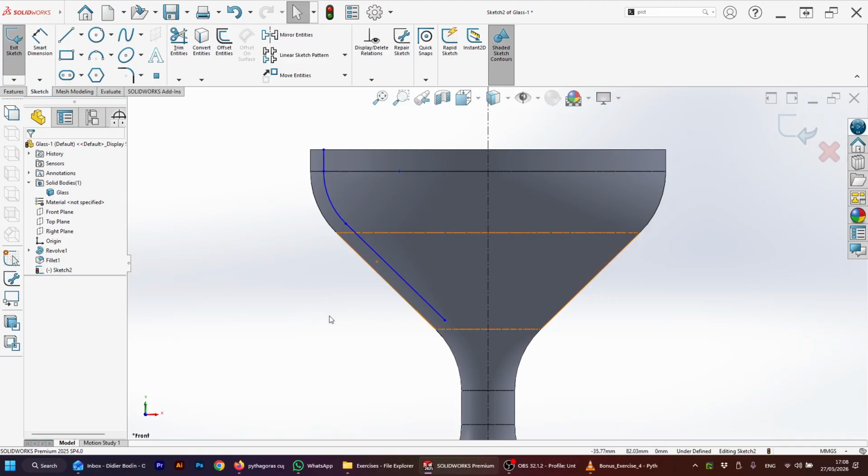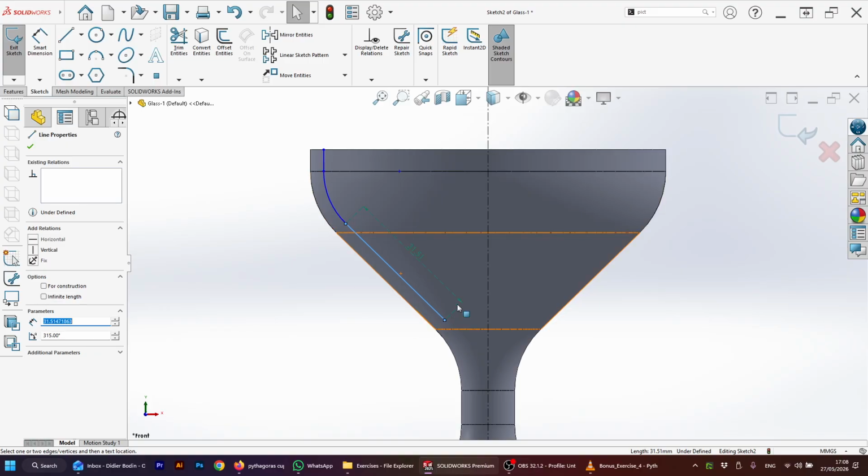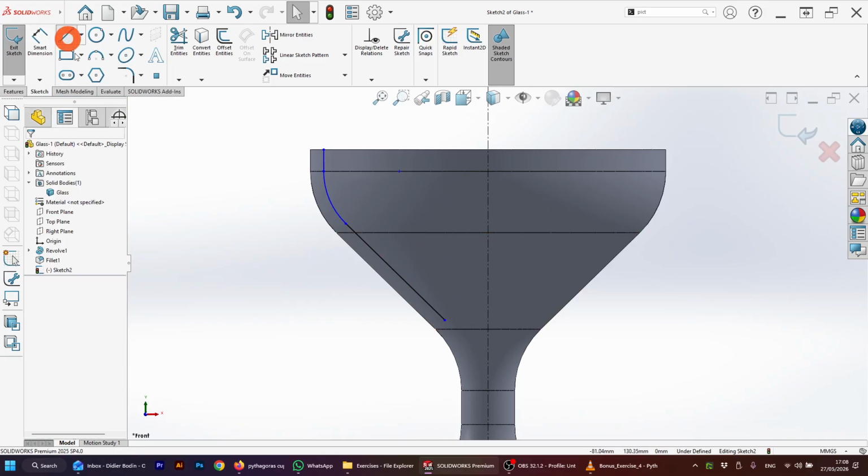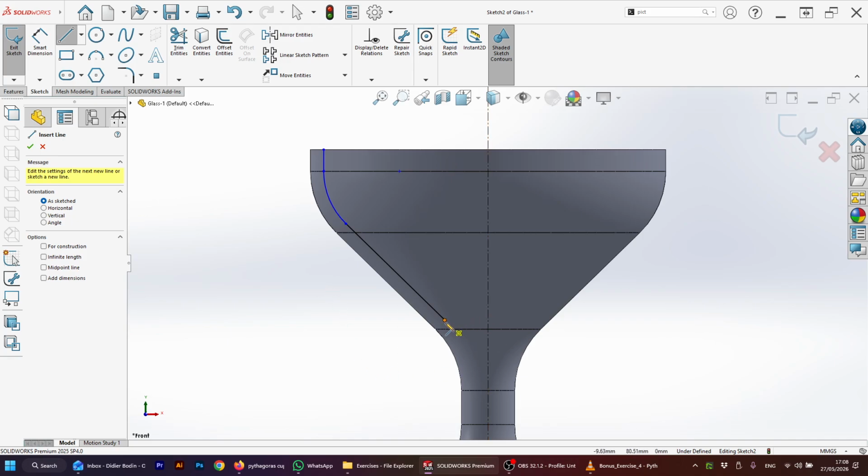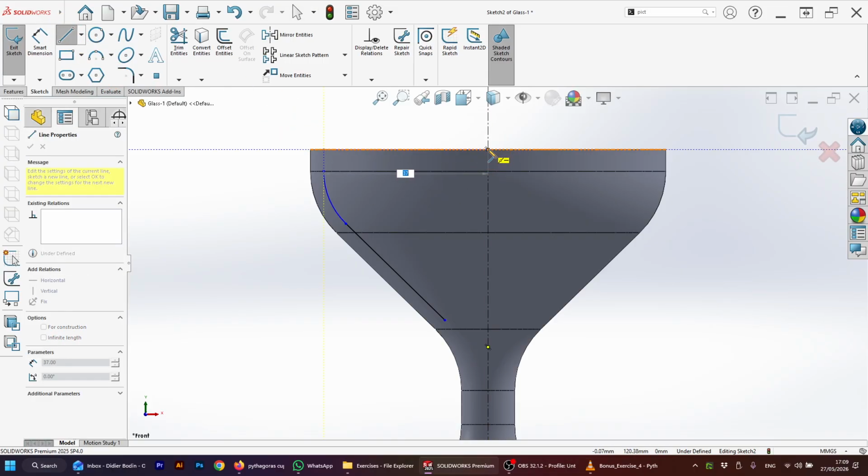Okay. Now, before we continue, I want to control where the bottom of my cap will be. So I can click on the line. I want this line to stay there. So I will click on fix the anchor, the origin, so it will not move when I do the next part. And I will continue to sketch using regular lines. I'm going to close. Here you can even do it that way because we are cutting through. Here you can see they're helping me be aligned, and I click on it.